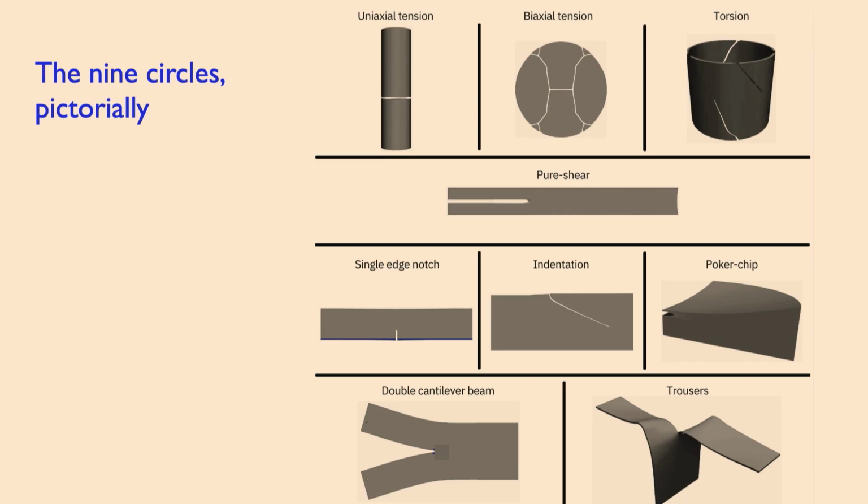Okay. Hello. So your model has a failure stress envelope. Which is necessary because, as the experiments show. Previously, you've developed cohesive models that have a failure energy in some sense, which you can interpret as a stress. And of course, they don't vary with the biaxiality, so they're not appropriate. But the terminology around those is that they're cohesive, right? Because they have an independent failure stress and an independent Griffith energy. But you don't use those terms for this model. I was just kind of curious how you're making the distinction between those cohesive ones and this one.